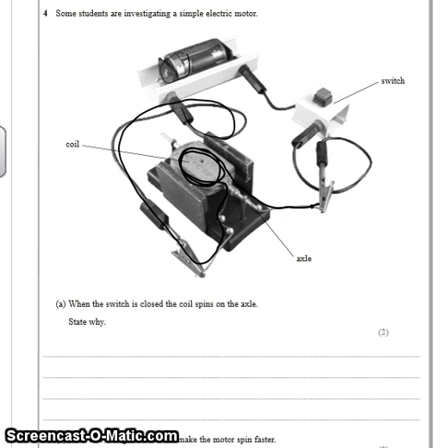there. Now, as soon as we've got current flowing through a conductor that's in a magnetic field, then we may well get motion. The magnetic field is going to be across here. Again, it's difficult to see which side is north and which is south, but what we know is that at some points within the coil we've got current that is cutting across the field at 90 degrees. As soon as we've got current and a magnetic field at 90 degrees, we can apply Fleming's left-hand rule to give the direction in which that conductor will experience a force.